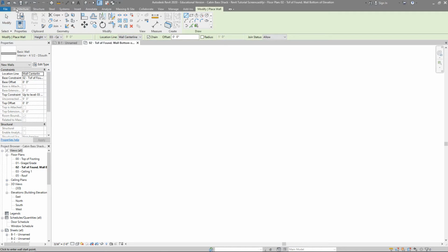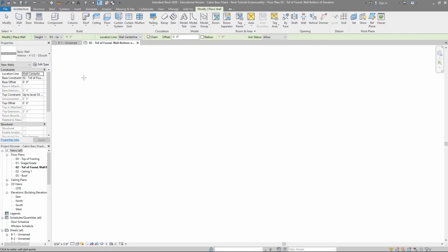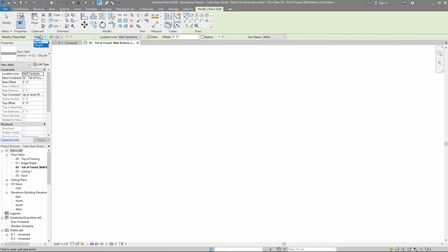When we go to click a wall, architecture wall, it gives us some options. Do we want to go up or down? What level do we want to go to? This is grayed out because the levels are controlling the height. And then where do we want to measure where we're going from? Right now, we want to draw a wall that's going to be 26 foot 3 inches. So we're going to pull across measuring on the top 26 space 3 inches.